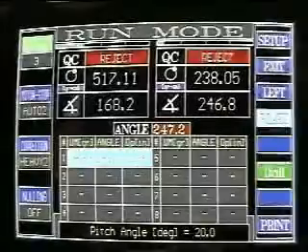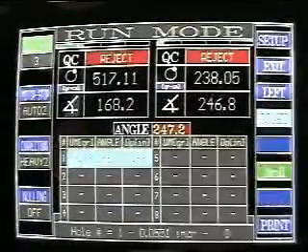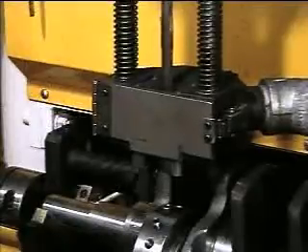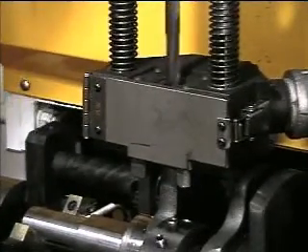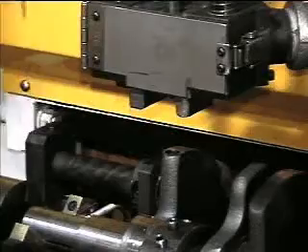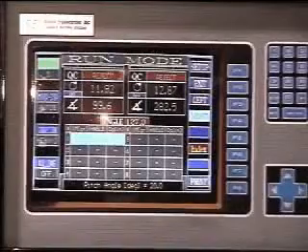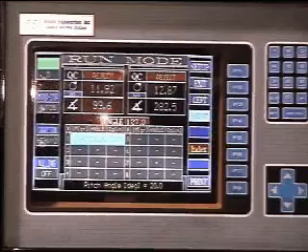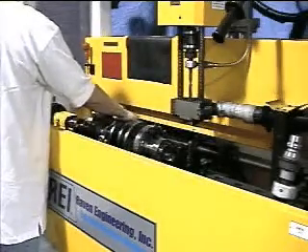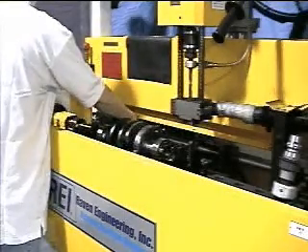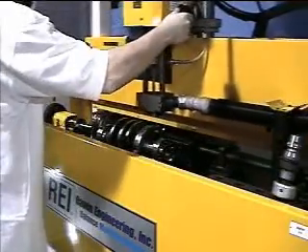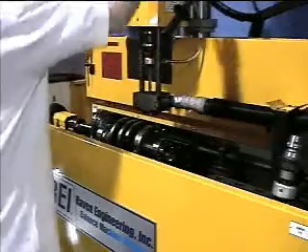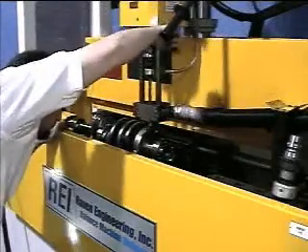When the drill touches the part surface, it is indicated to the HBI-25 via a torque monitor, and the HBI-25 then controls the depth of the hole. Hole depth is indicated in real time at the bottom of the correction screen.